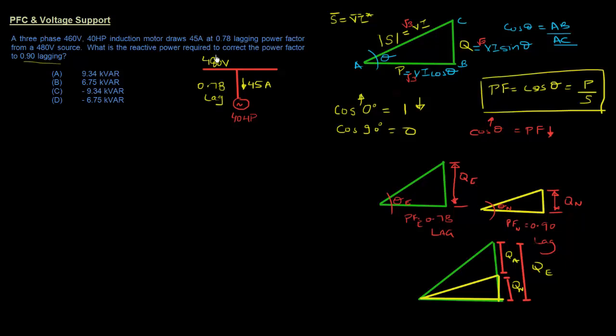So what's the reactive power required? This is the reactive power that is required to change the power factor from the one that corresponds to theta existing to the one that is with theta new. That's the reactive power that needs to be added to the system.